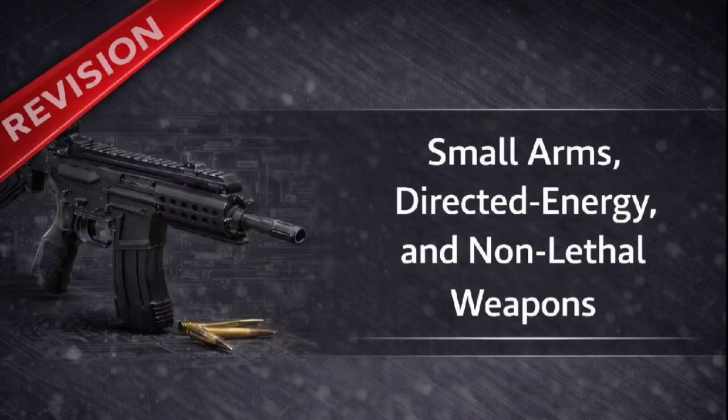You've now completed a thorough revision of the layers of small arms technology. To quickly summarize our journey, small arms are defined by their caliber and their mission, driven by 5 core requirements including tactics, logistics, and accuracy. Then we move to the mechanics. Automation relies on the foundational 10-step operating cycle, powered by recoil or muzzle blast. This manifests in 3 major mechanical systems: the heavy, simple, unlocked blowback, the sturdy, locked recoil system, and the adaptable regulatory gas operation. And getting the shot on target.